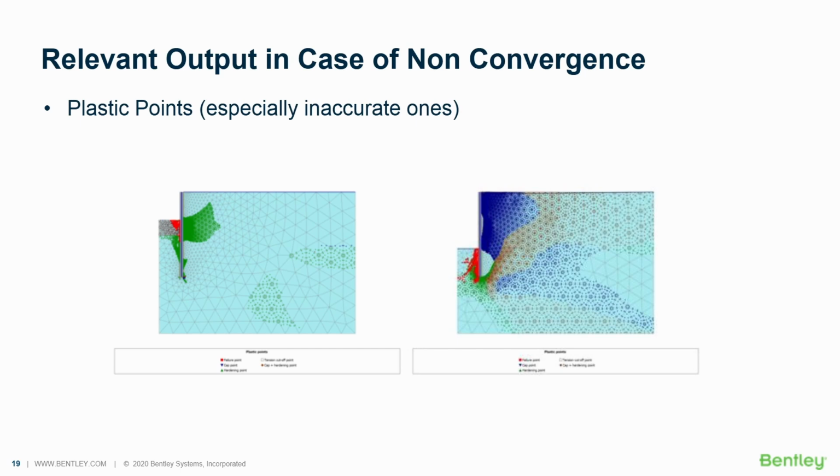We create plasticity before failure just for the sake of having a nonlinear stress-strain relationship of the model, which is characteristic of soil. But the hardening points are not failure points. So they are not points to be concerned about. The white one and the red one are.